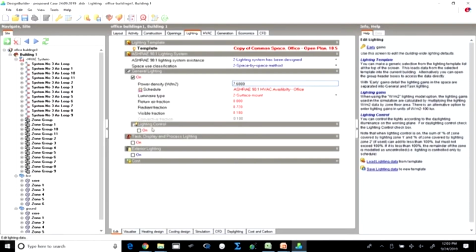These photosensors will have a threshold limit, a cutoff limit. Say if the outdoor light falls below 1000 lux, that is when the artificial light indoors will be turned on automatically. All other times, when the threshold is not met or the outdoor illuminance value is higher than this threshold, the artificial light will not be turned on. So, this is what the lighting control is.